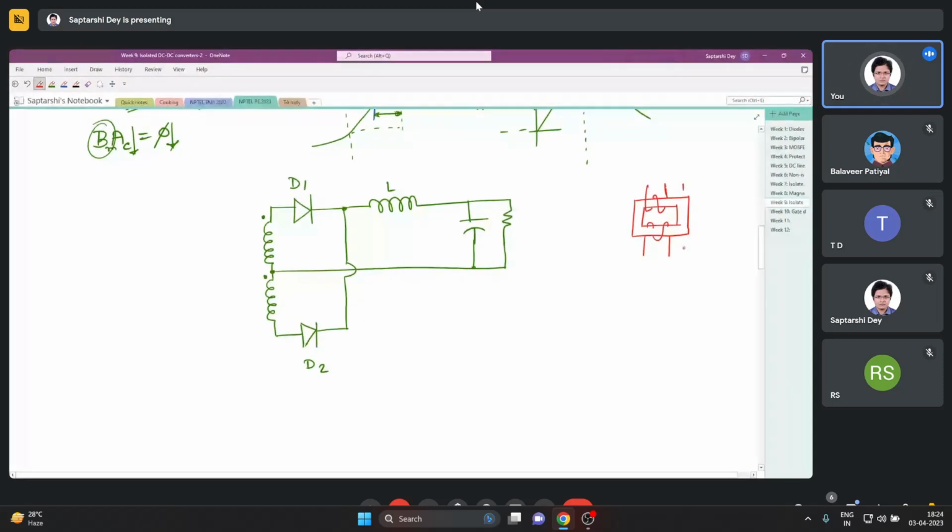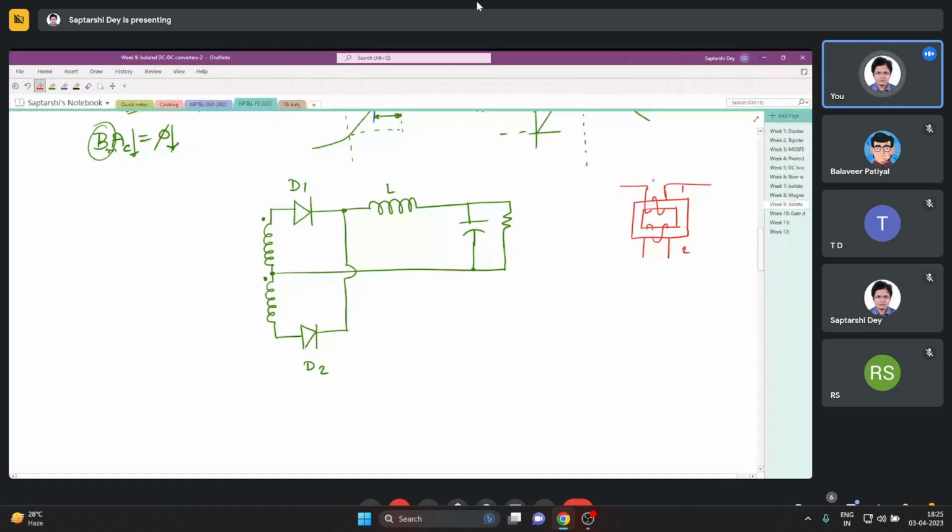So you have two sides, one, two. You open this side too, do not connect anything here, and this other side you can connect to a circuit, and this will simply act as an inductor. This is nothing but a solenoid. I'm talking about practical transformers. So what is the inductance value? That inductance value is nothing but Lm.